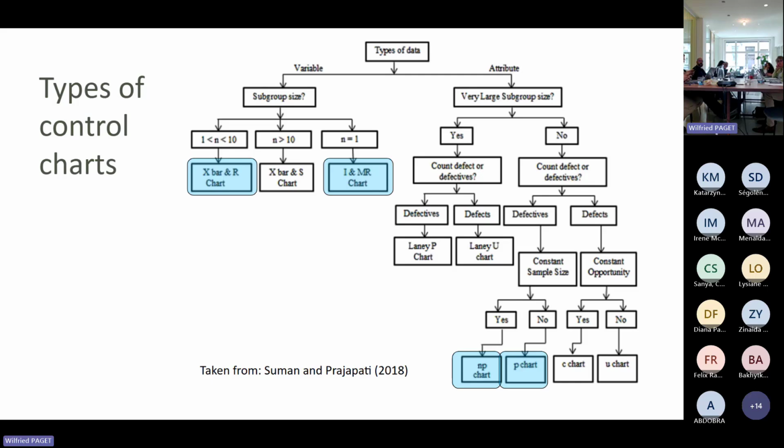If the sample size is small, instead of computing a standard deviation, we use the range in that sample. Of course, if we have a big sample size, then we can go to the mean and the standard deviation, but usually we don't have samples higher than 10, so we rely on X bar and R bar. And if you are in categorical variables, usually we use proportions defective, and there is what we call the P chart and then the NP chart.